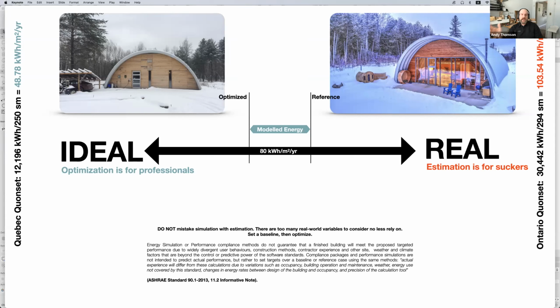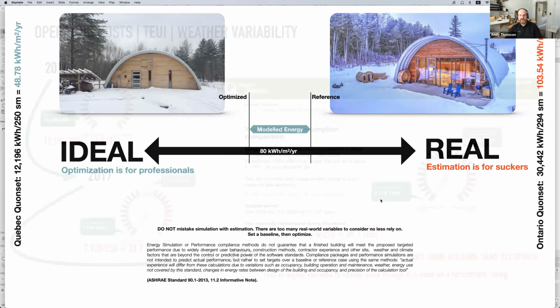and the reality. In our case, the EUI of 50 was less than 80, which was the predicted from the reference model, just because we're really conscientious users. We use hardly any water. We run our thermostat at 18 degrees Celsius. We set it back at 15 at night. We ventilate instead of running air conditioning. So these are all things that are super important in an energy model.